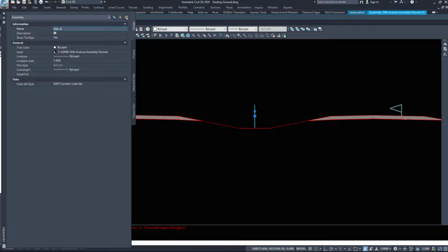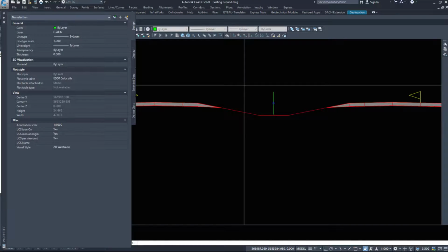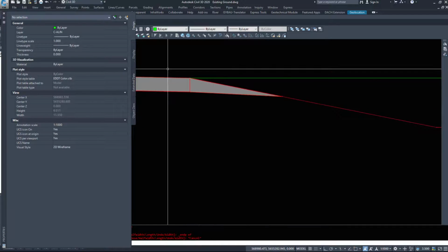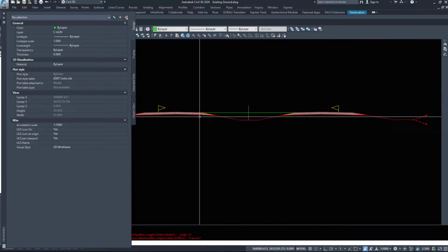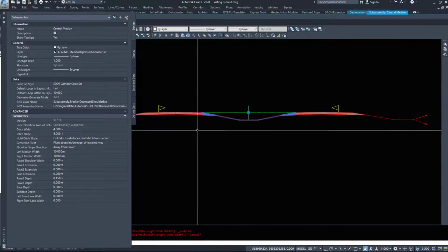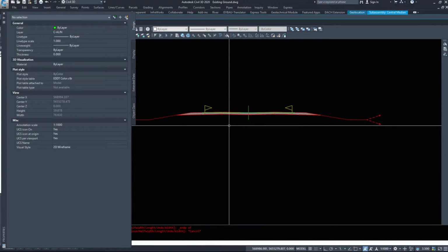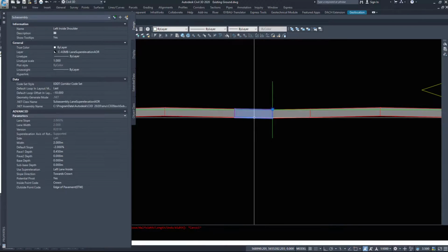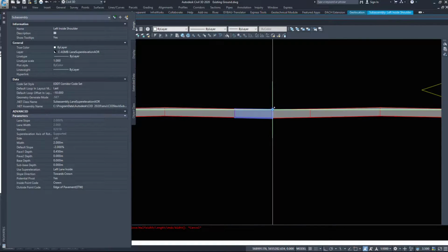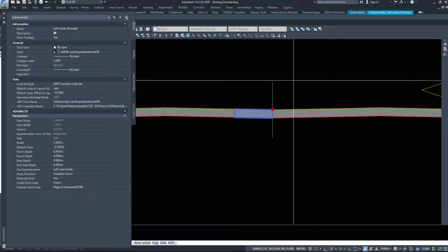The first thing I'm going to do is rename this centerpiece: 50th Avenue Assembly Bridge. Now I'm going to cheat a little bit here. I'm going to draw a polyline from these 2 points because we're doing the bridge piece now, so we're going to build 2 independent bridges of each other with no median in the middle. The reason I drew a polyline from side to side is for when I delete that piece. Again, just select the median and delete.